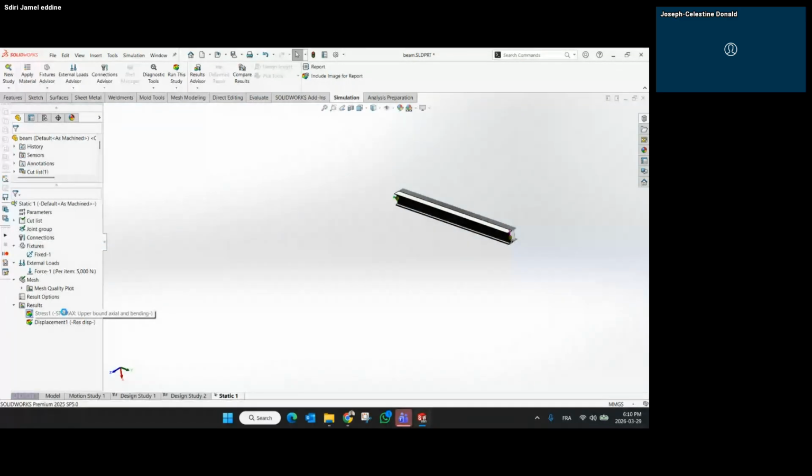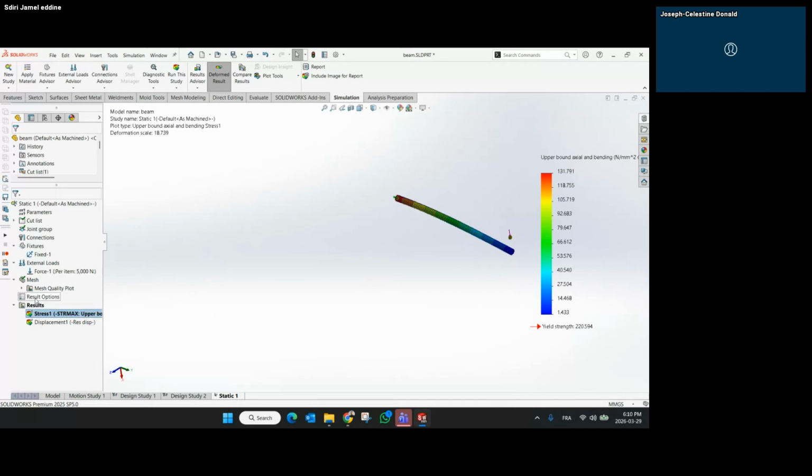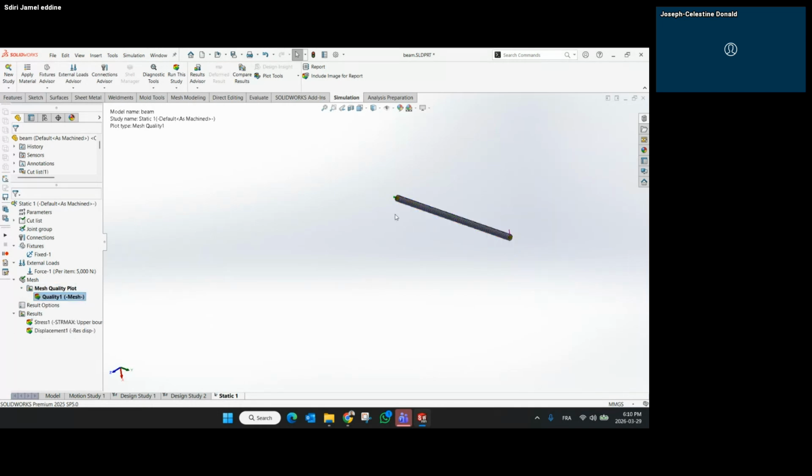As you can see here, it's modeled as a 1D mesh. Even for the mesh, it's modeled as a beam part. It's not modeled as a 3D part, or you cannot model it as a sheet part, but as a 3D part. Yes, you can have all three, and also you can have 2D simplification.